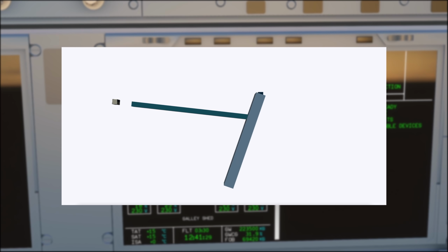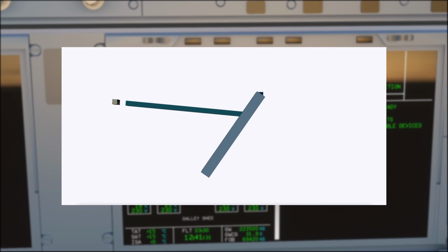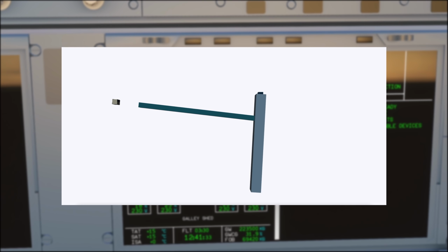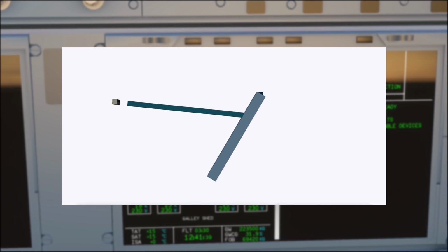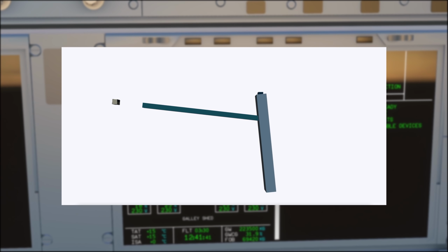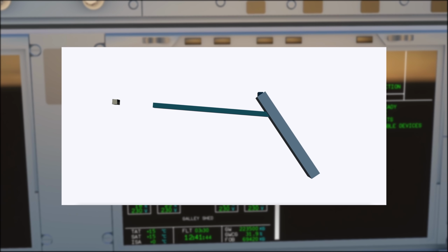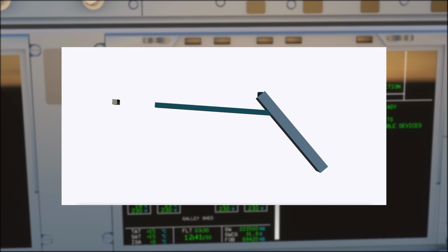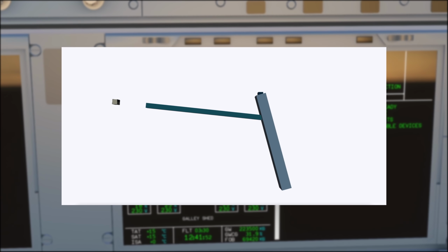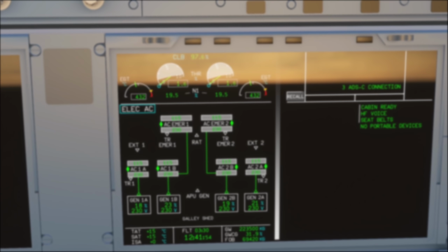We are also using these actuators on all flight control surfaces, such as ailerons. Therefore, if a hydraulic system fails, the connected actuators would automatically stop working. This means surfaces moving at half speed when appropriate, or drooping once on the ground with all engines off. Once an API is available in the simulator, we also intend to exert aerodynamic forces on the surfaces.